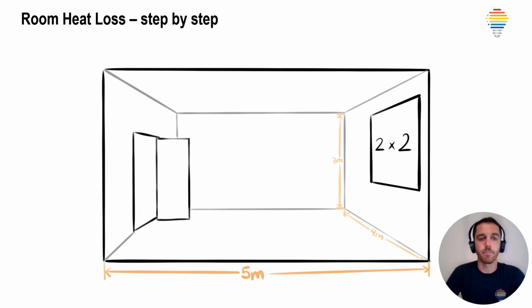So here is an example of one room. If we have a room like this, this wall is an outer wall with one window. This wall is also an outer wall, and this wall is an inner wall. We'll cover this later. So we have dimensions, how big the room is, what the height is, so we can calculate heat loss by each area.